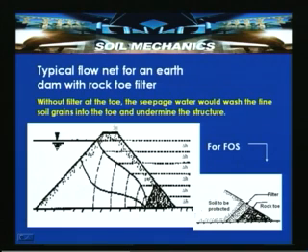Here a cross section of an embankment dam has been shown on the toe side, and you are seeing a rock toe with a filter. The details shown in this small window are the soil to be protected, that is the soil used in the embankment or earthen dam for construction, and the rock toe, which serves this purpose in preventing the undermining or piping failure of the structure.